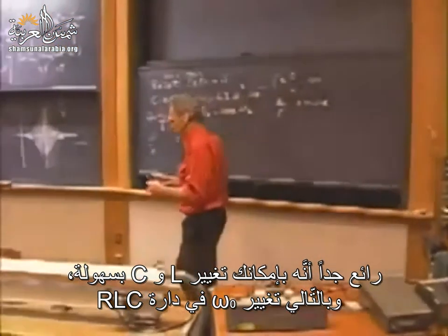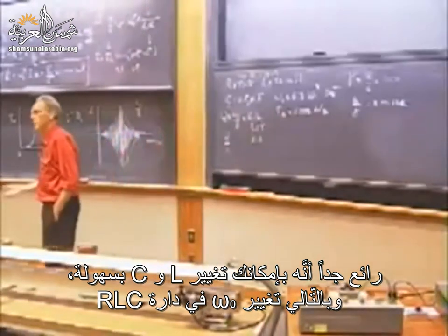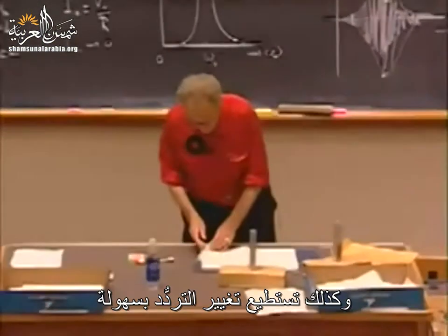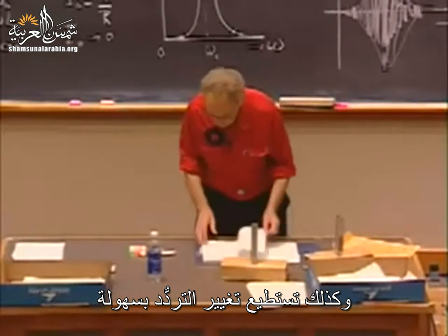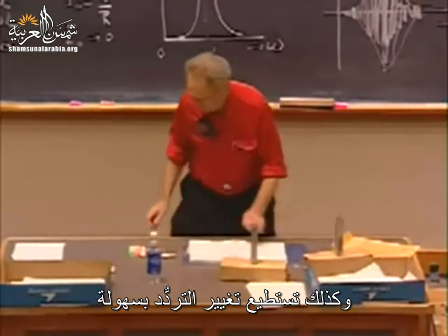You see, it's down by a factor of 2 from here to here. And you may have noticed that it also gets broader. And now I will go to 150 ohms. And you see it's down by a factor of 3. And again, it is broader. So this is an amazing way how with RLC circuits you can do wonderful things, because you can manipulate omega 0 very easily by changing L and C, and you can manipulate the driving frequency also very easily.